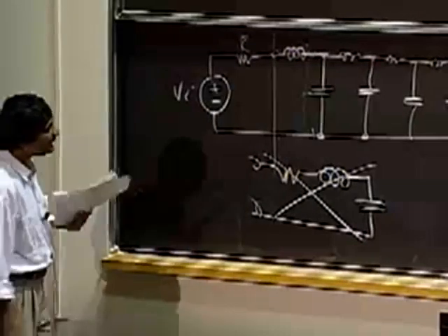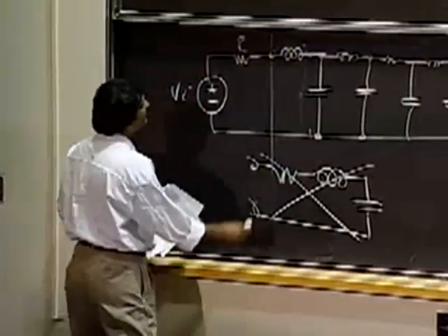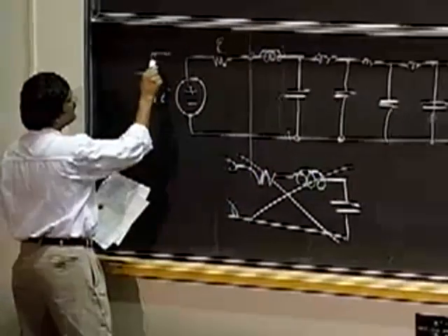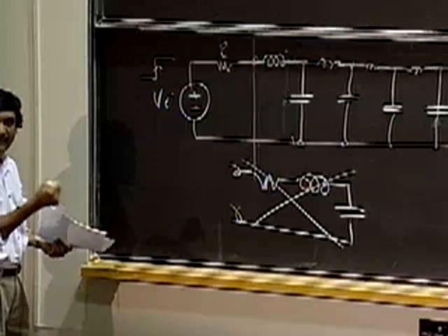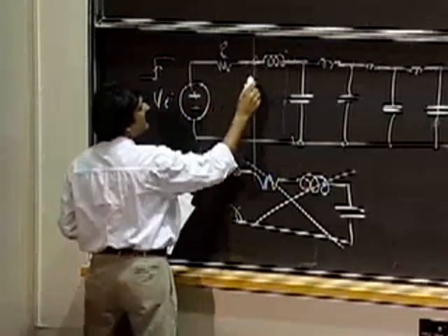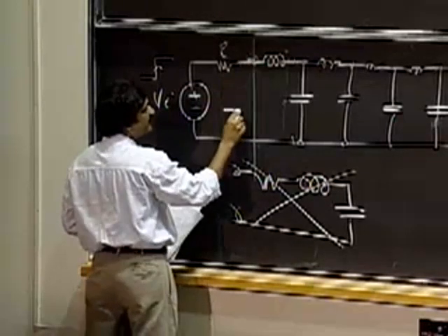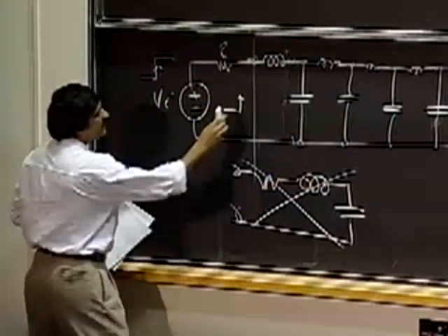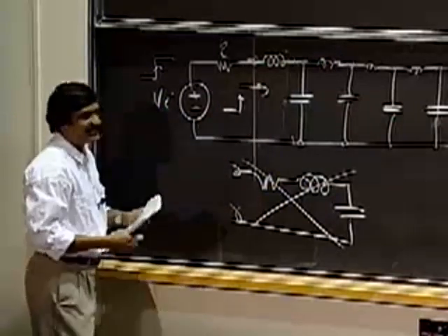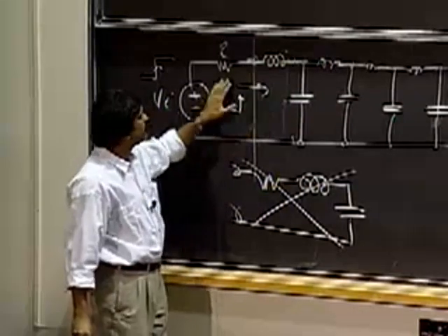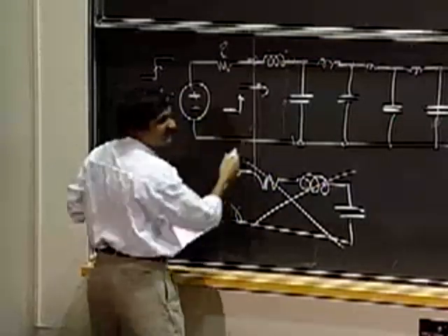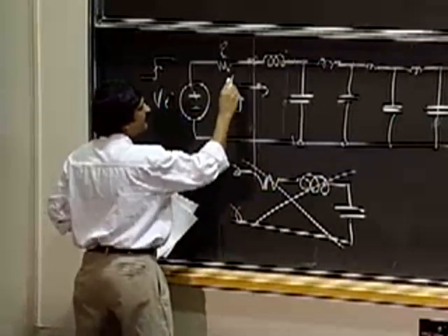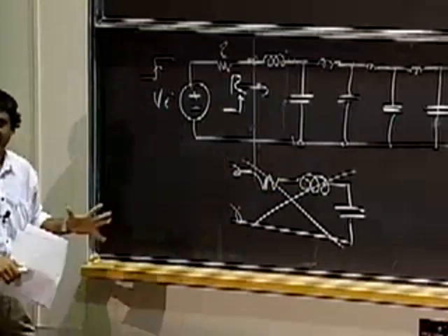We need to see what's going on. So what's happening here is that at time t equals 0, I get this step. Think of that as a pulse of energy. And the instant it comes here, instantaneously, this looks like a voltage divider. I've chosen my resistance R here to match the instantaneous impedance looking in, which is also R. I've just arranged it to be that way.